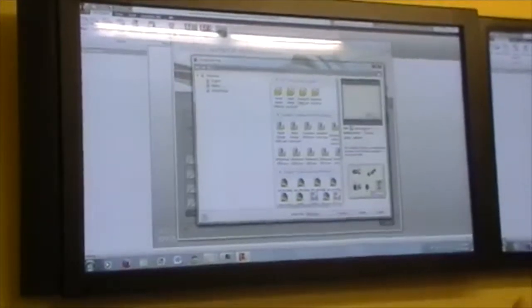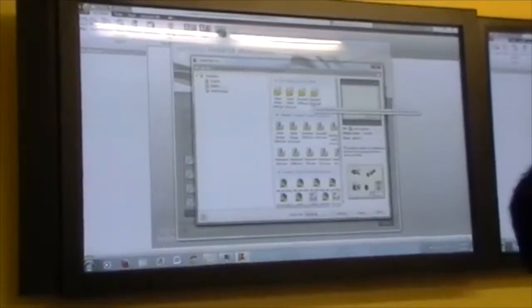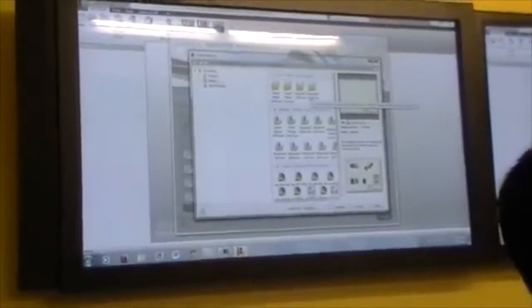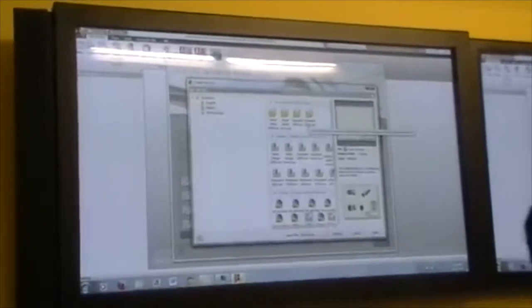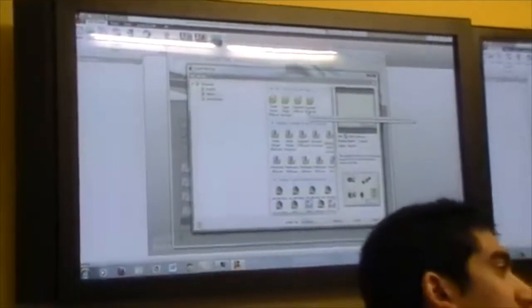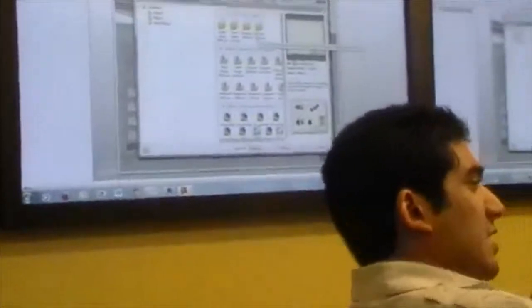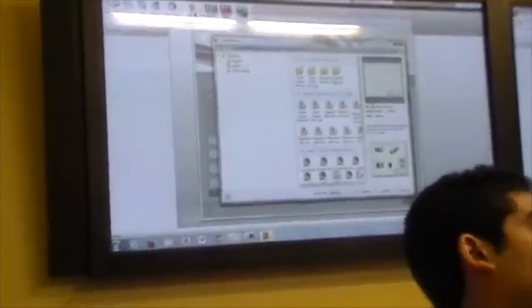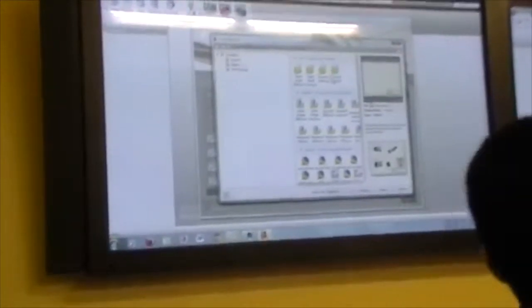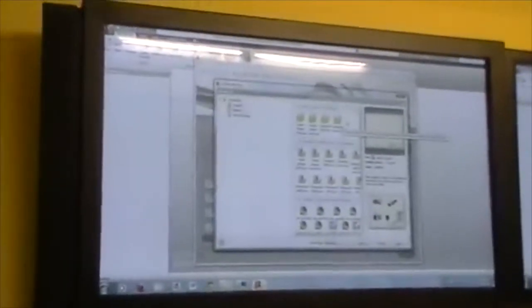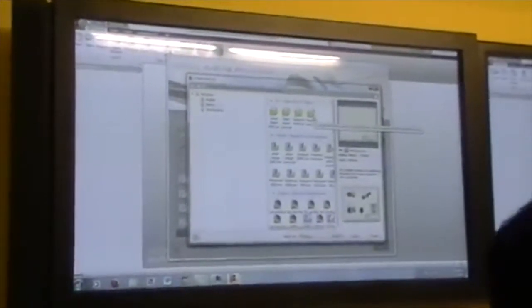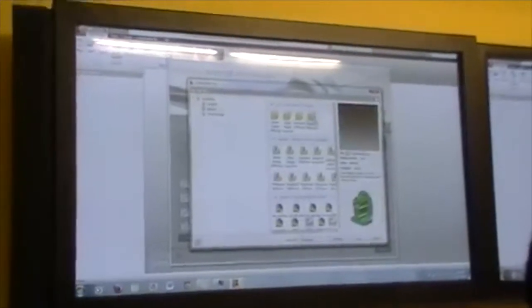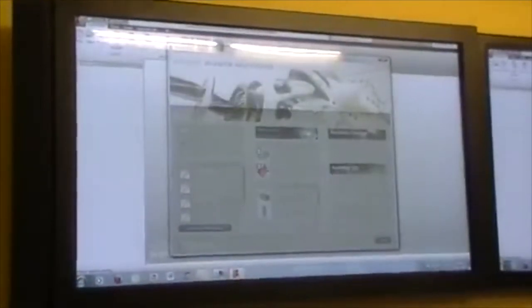Now, sheet metal modeling versus standard modeling, the biggest differences there are you get some additional functions in sheet metal modeling, where you can bend, you can kind of flange, these different functions that are only relevant for sheet modeling. So typically what you're going to go with is a standard millimeter .ipt. .ipt is the file extension for a part file. So let's go ahead and create one.